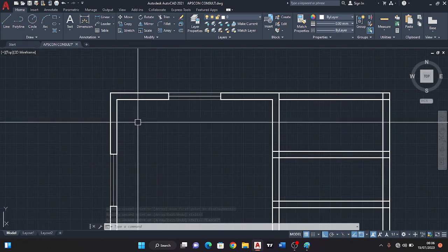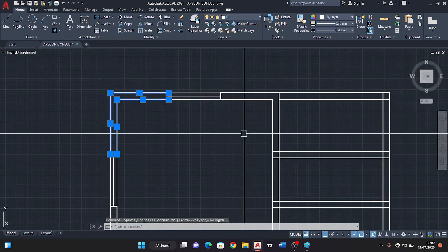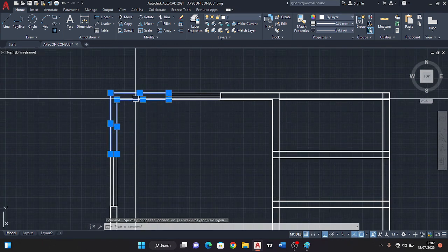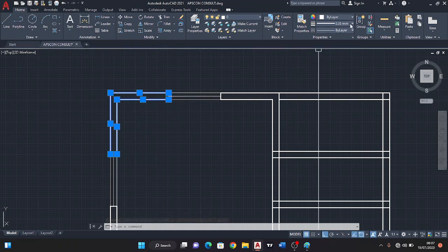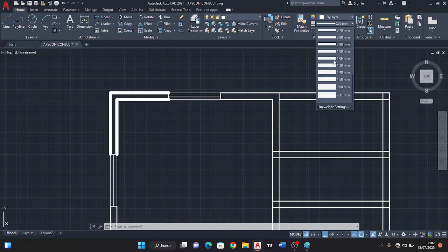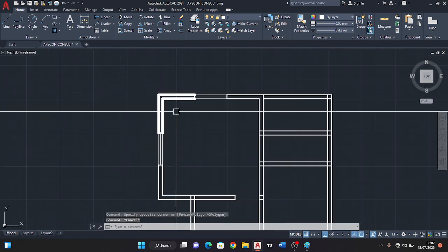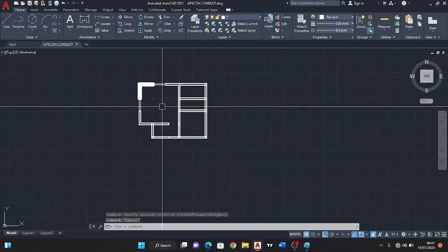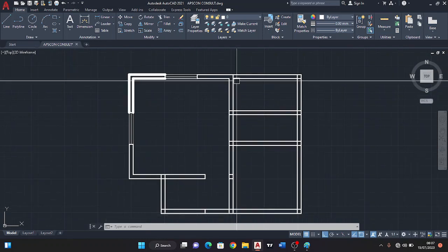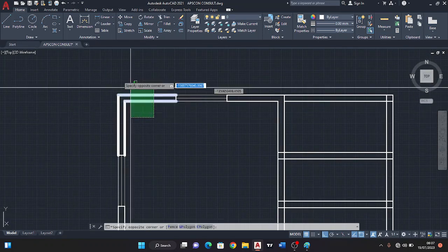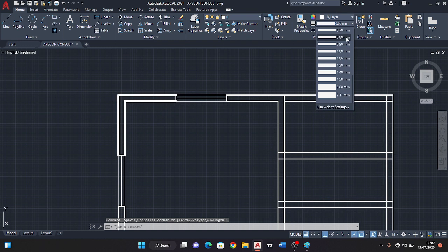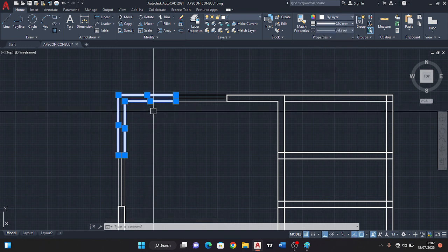Actually, this is my window. I can increase the weight of this line. Select the line, come to here, it shows the properties. I scroll down. I feel like I want to increase it to, let me say, 0.8. Now that's 0.8. If you watch, it's only this line that has that weight. Others are still the former way. Let me reduce it. It seems very thick. Now let me reduce and use 0.6.